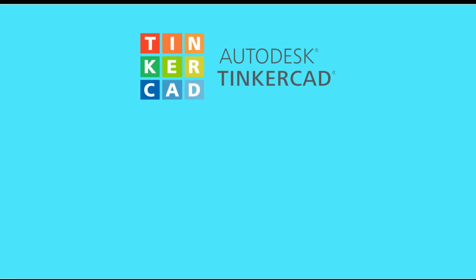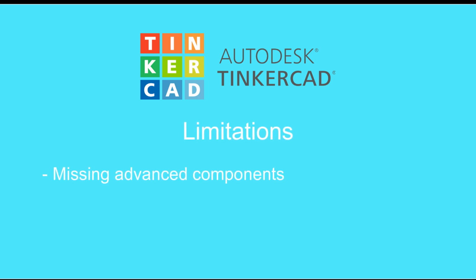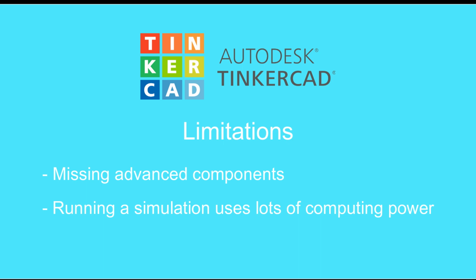As you can see, TinkerCAD is super useful and super powerful, but it has its limitations. It's missing many of the more advanced components like stepper motors, OLED displays, and moisture sensors, just to name a few. Also, running a simulation is surprisingly highly computing intensive, especially for older computers like mine. And this won't really be a problem for most modern laptops, but if you're like me, you might want to close a few tabs before running a simulation. Lastly, I think the programming IDE can be a bit more powerful. Things like a dark mode and autocomplete features that are commonplace in most IDEs would be a welcome addition.